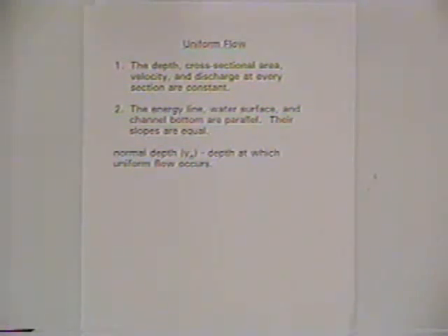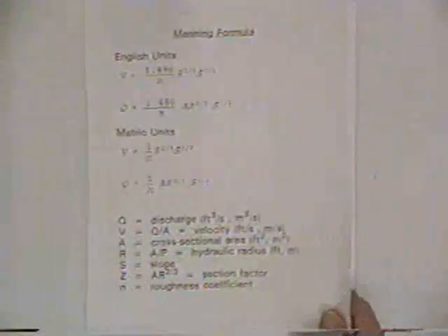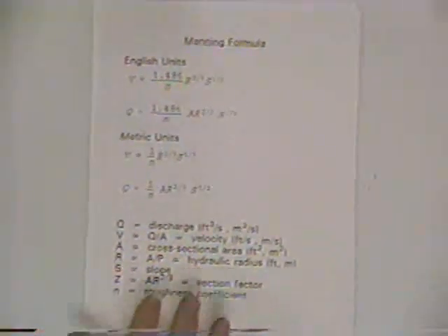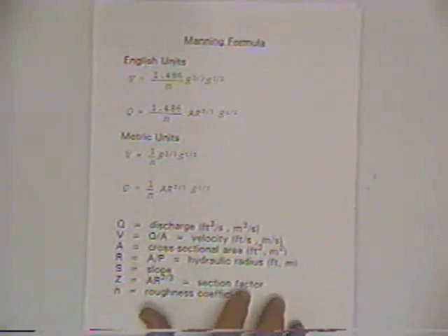And so we're planning for open channel flow problems on the exam to limit themselves where we recognize that this is a uniform flow problem. And so we can use the one equation that's provided in the reference handbook, and that's Manning's formula, to deal with flow situations as far as a uniform flow equation. Now, energy equation, the basic concepts are equally valid to uniform open channel flow as well as pipe flow. And so here's Manning's equation.